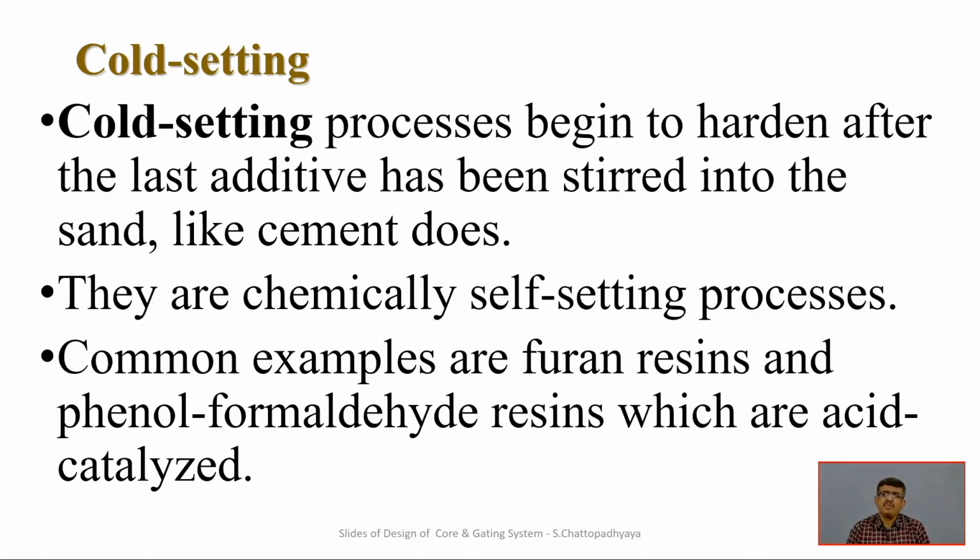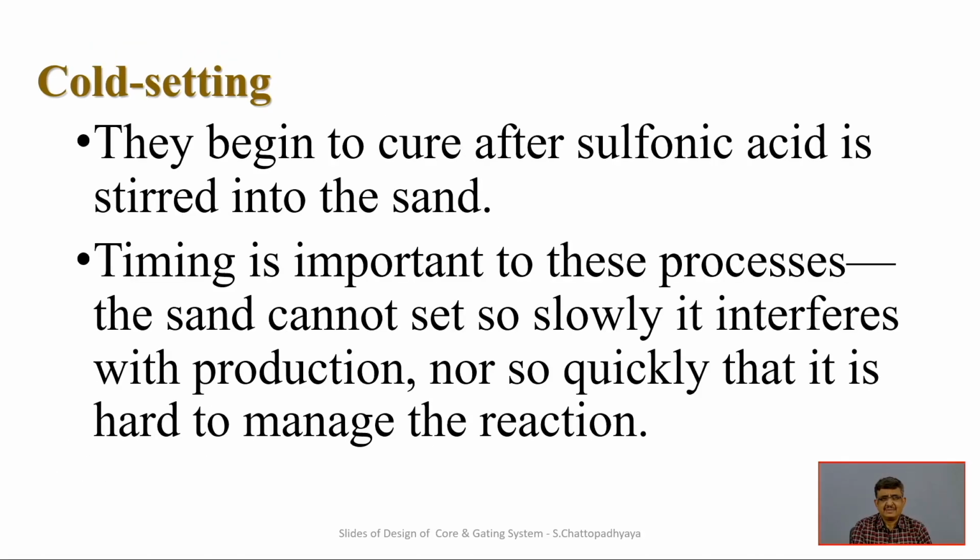They are the typical properties of all those organic compounds, or the phenol-formaldehyde resins, which are acid catalyzed with some kind of acid environment, and that way they ensure the binding of those sands. And they begin to cure after sulfonic acid is stirred into the sand.